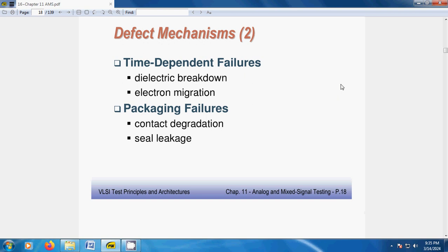It may be due to the temperature within the IC. As you already know, when an IC operates, a lot of temperature islands are created within the submodules. Whenever a particular submodule works at a higher frequency or a higher speed than the nearby modules, that high speed module accumulates more heat than the other modules.